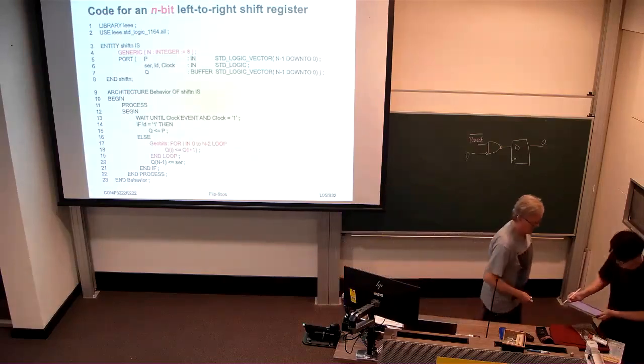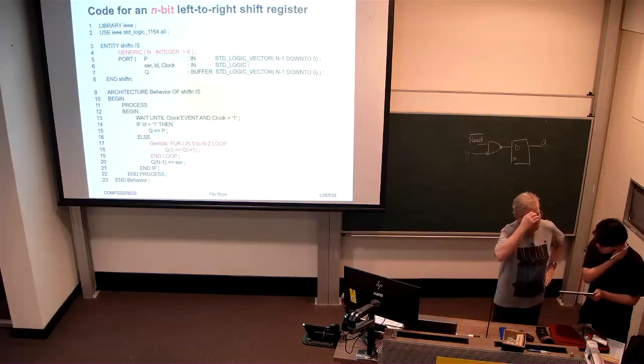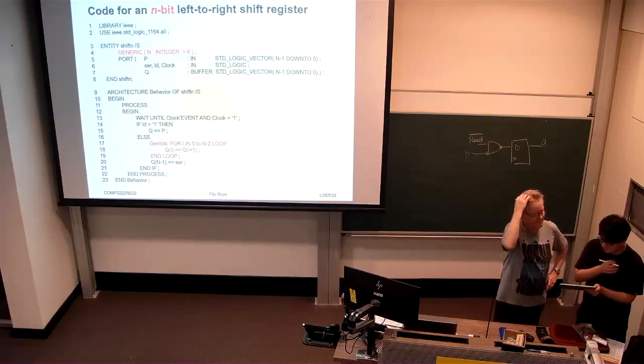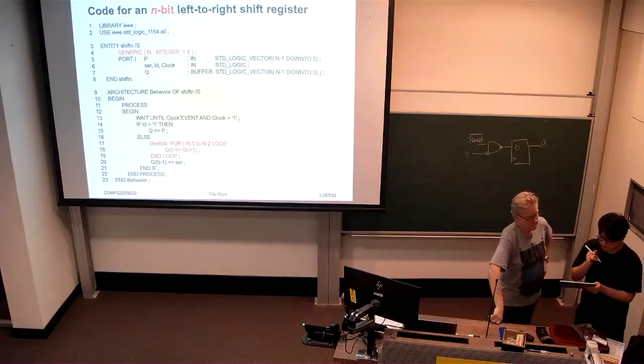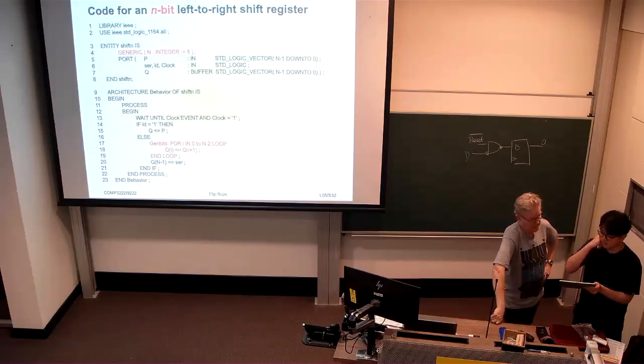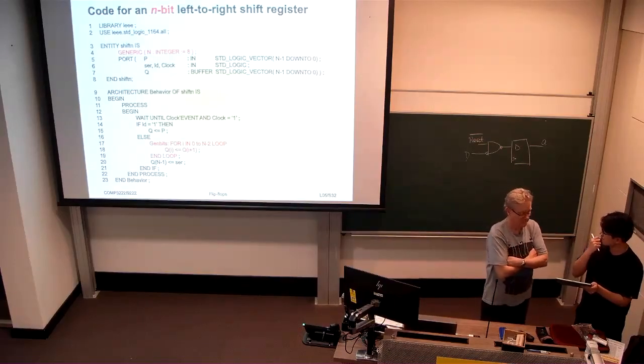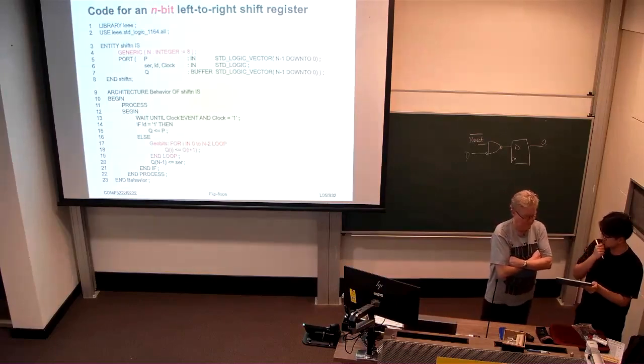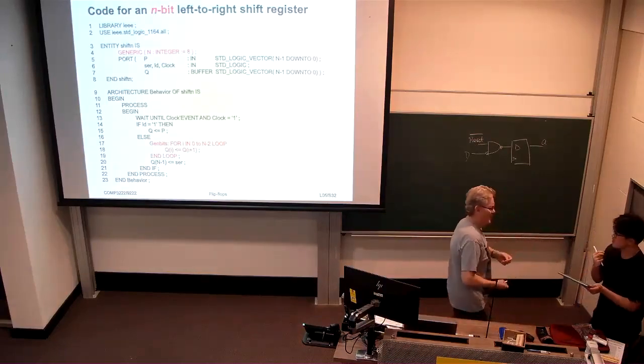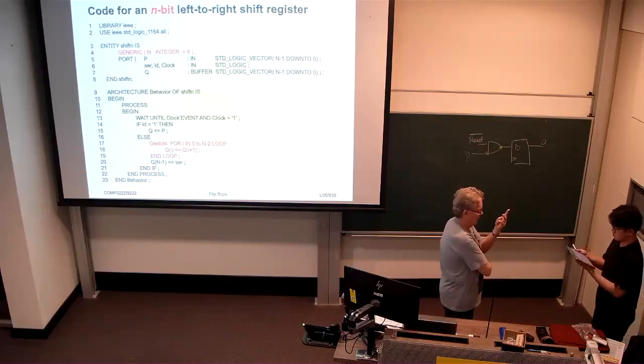Just for this exercise, I'm not too sure if it's right, because it did say simplest. We have to design a circuit to determine whether two 4-bit numbers are equal. Yeah, but the one it came up with uses subtraction with a 4-bit adder, and it just subtracts to see if the result is 0. I feel like it's a bit too much. So what if you just had two 1-bit inputs and you wanted to know whether they're equal or not?